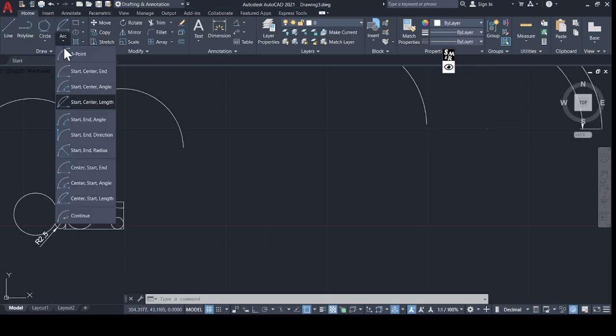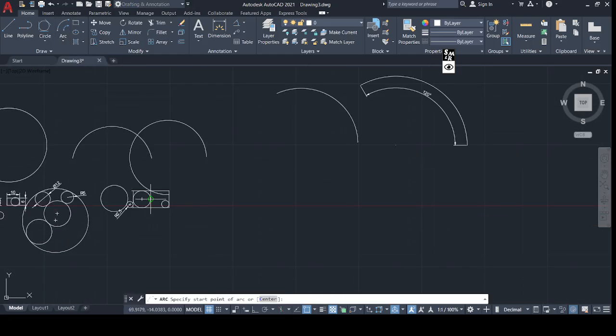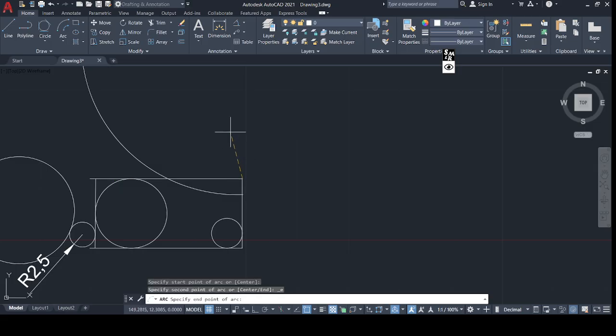So go to the arc command, start and angle. Let's take an example of this drawing. I am clicking the start point and the end point over there. Now you can clearly see this is the 0 degree angle, and if I go in this direction, 90 degree angle arc, 180 degree angle arc. Understand? So if I put the value 180 and enter, the 180 degree arc angle has been created by using the end to end point. Okay, so this is how we can create it.